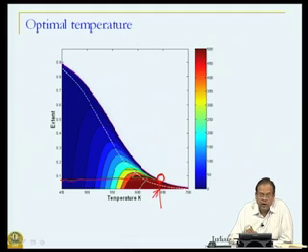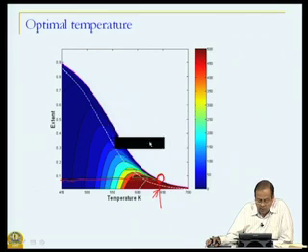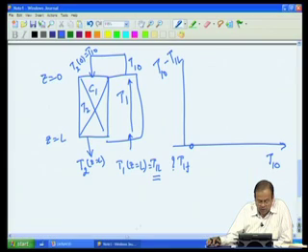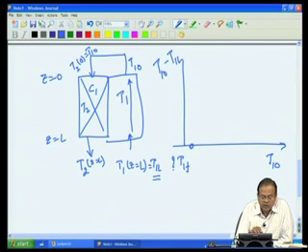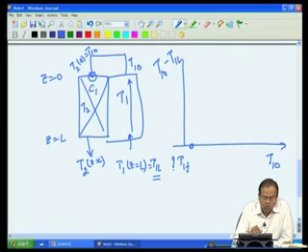So, if at the entry point I have already achieved my equilibrium, then what will happen in my reactor? In my reactor, no reaction can take place, because if the conditions at the entry point are such that we are at equilibrium, then the reaction can't even start. So, there again won't be any reaction through the entire reactor.